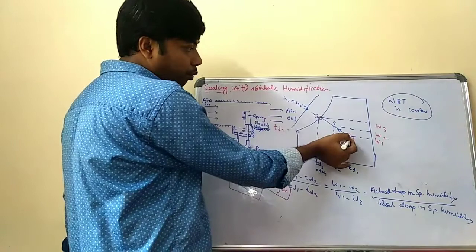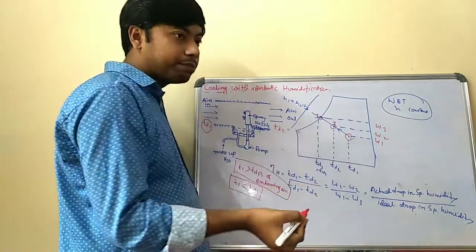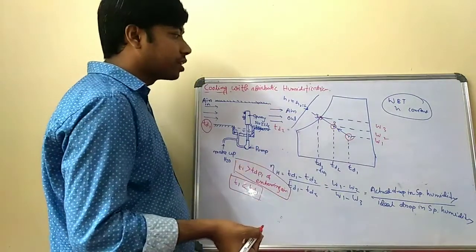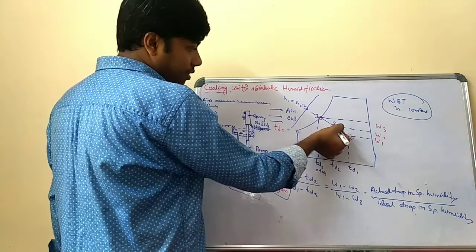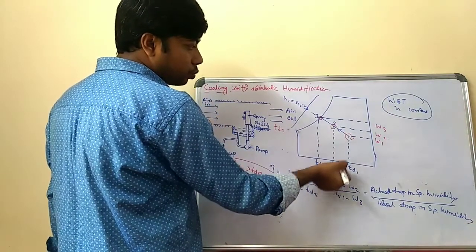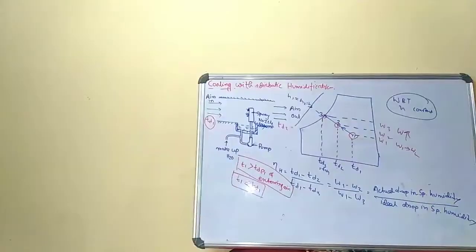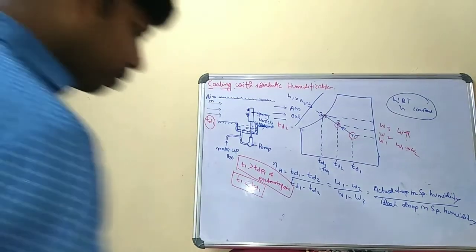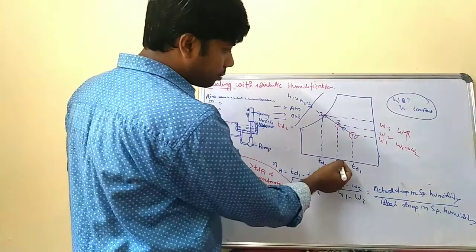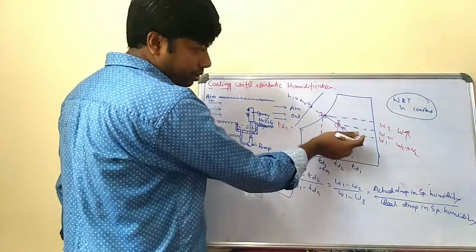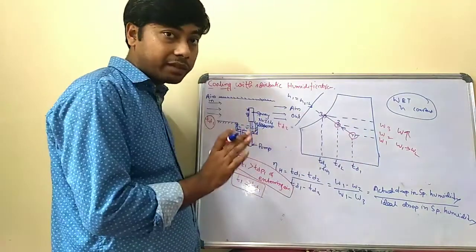There is inefficiency of the cooling coil. Suppose between point 1 and point 3 there is some point, which is basically the effective point reached in the cooling and adiabatic humidification process. So assume that corresponding point has dry bulb temperature TD2 and specific humidity W2, where W means specific humidity. This is point 1 and this is point 2. If the process goes from 1 to 3, it should be ideal, but that is not possible.